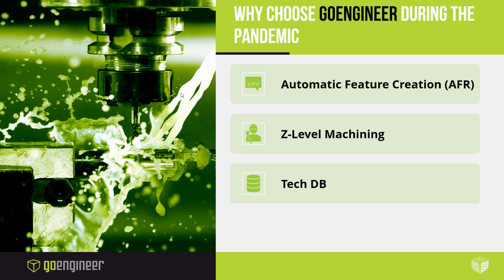It currently is a 2.5 axis system, which means that you can cut in the X and Y at the same time as you move your spindle around, and you can go up and down with your Z as well. So you can do pretty straightforward machining and even get into some higher level stuff, which is the Z level machining, which I want to show you guys and we will talk about a little later. The main thing to understand about the CAM system, though, is that it's really built around a tech database.